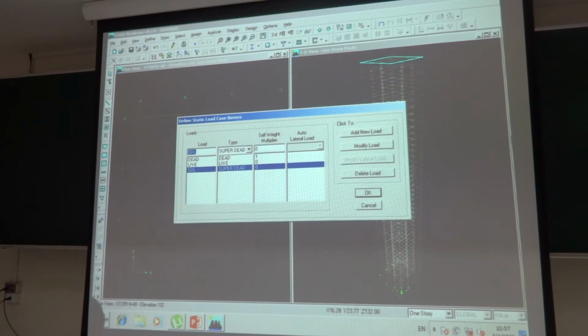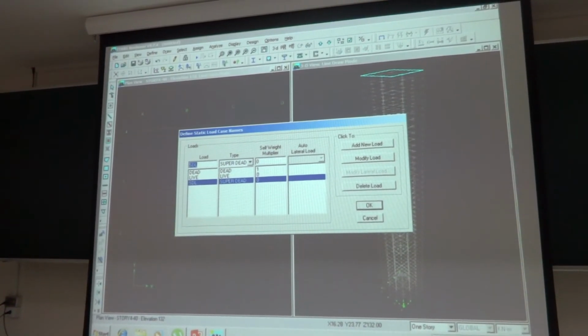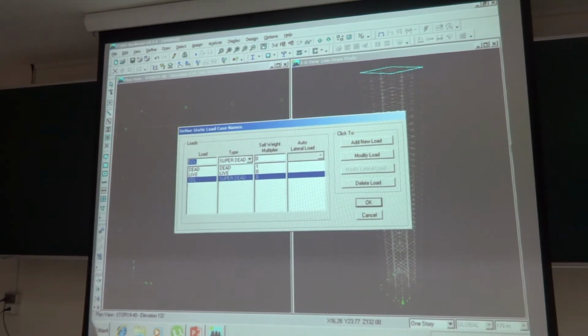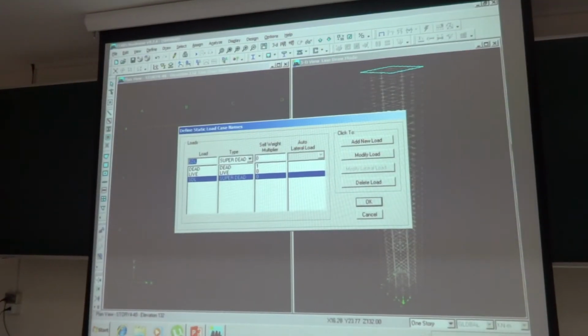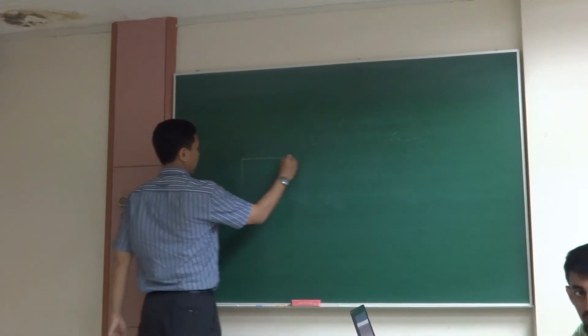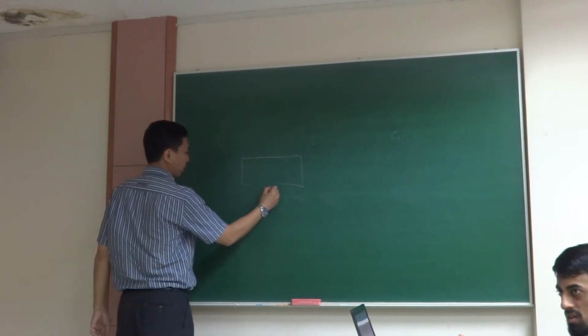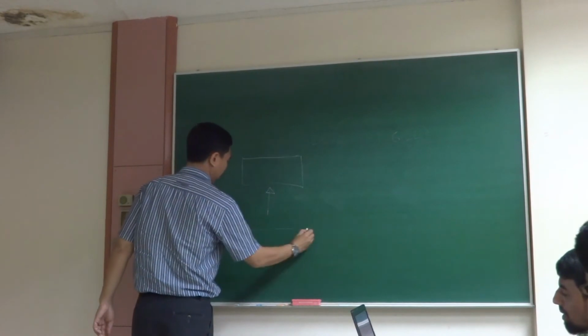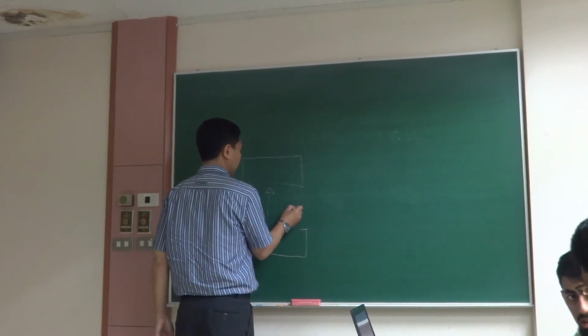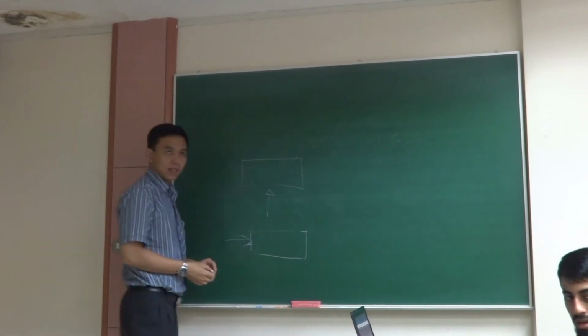and you have to specify the lateral load, wind and seismic load. For wind, we apply at least 2 cases, wind X and wind Y. But you cannot say always wind X and wind Y. Better to consider what is the maximum area of your building. If your building is like this, we consider X, consider Y, at least 2. But sometimes if the building area is larger diagonally, we should apply the diagonal direction as well.